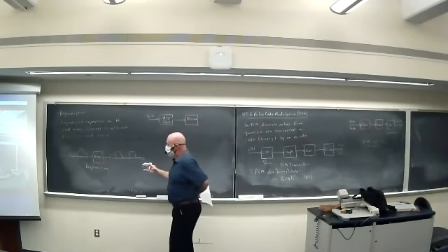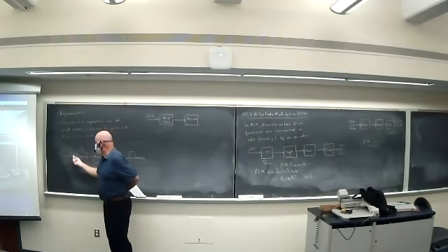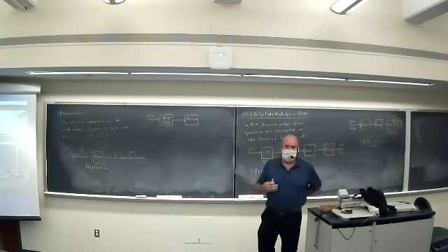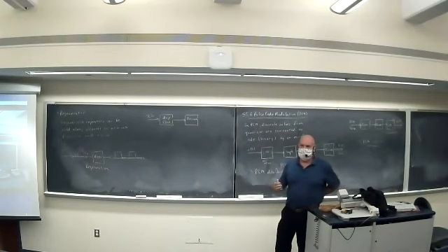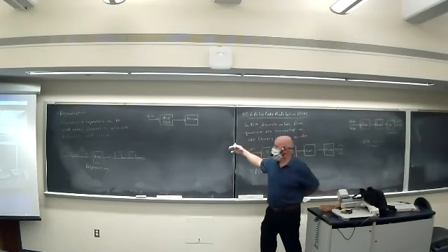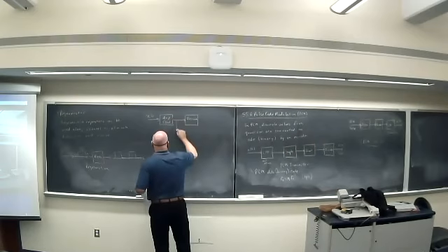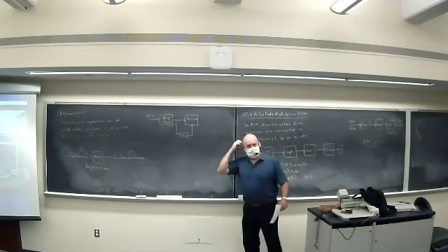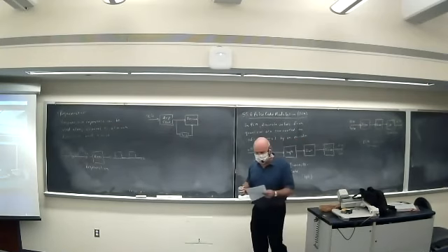I will sample the waveform at these instances, obtain the sample value, and compare that to, maybe if I'm expecting 1 to be 4 volts and 0 to be 0 volts, a 2 volt level. So I'll sample it and feed it to a comparator, but my decision maker does need timing information in order to determine when I take these samples. That timing information is usually derived from the waveform, and that's something we'll talk more about.